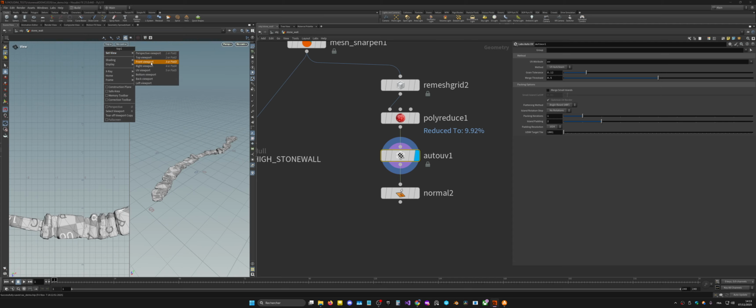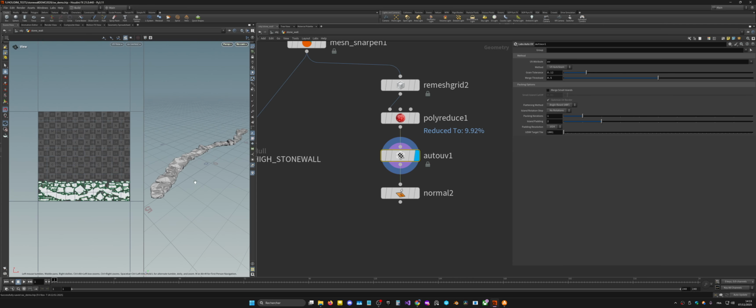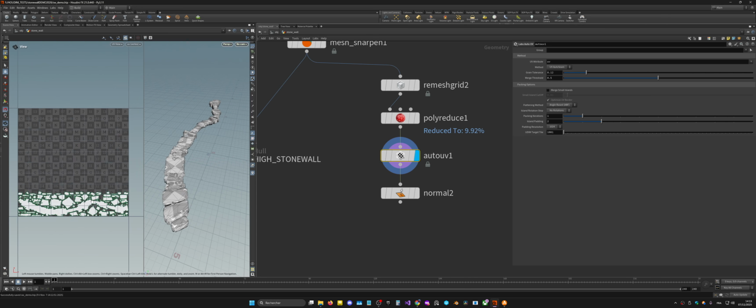So let's display the UVs. Unfortunately, UVs are very hard to get with automatic UVs. So it's working, but it's not optimized. As you can see, it makes a large ribbon like this. And as it maintains the scaling from the viewport, like the preserve 3D ratio in Autodesk settings, I'm losing a lot of space in the UV, so I will allow the algorithm to make more cuts